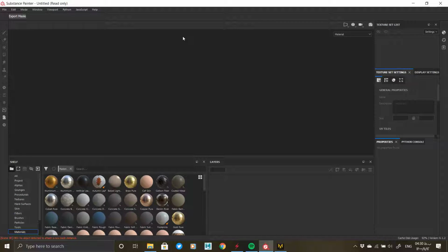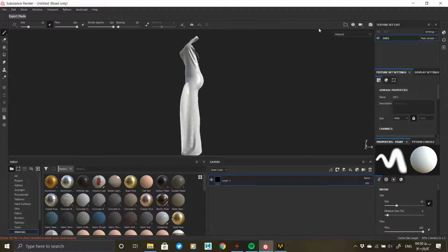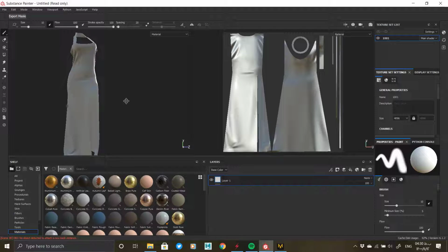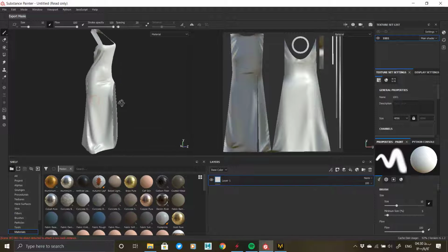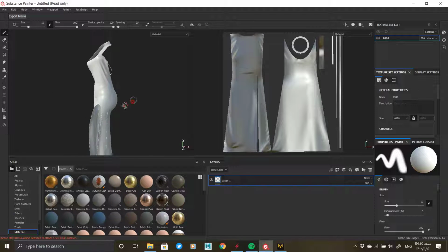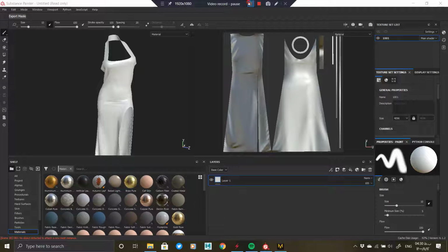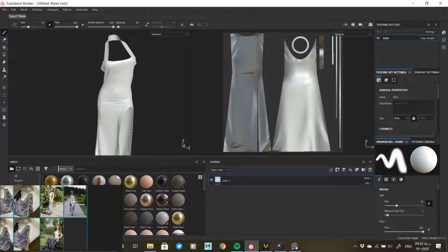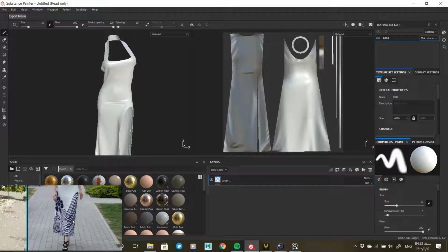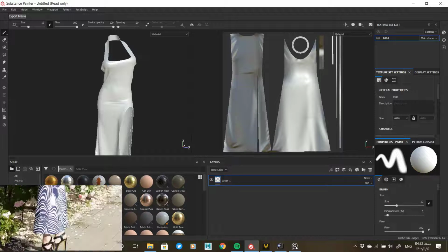Save the output as OBJ without characters. Select the single object mode, and choose one of the 3 modes, thin weld, thin unweld, and thick, based on our needs. In thick mode, the UV of the thick parts is not defined. So in the case of thick output, it is better to define UV thickness separately, for those parts in other software.